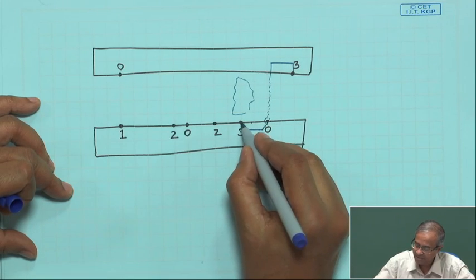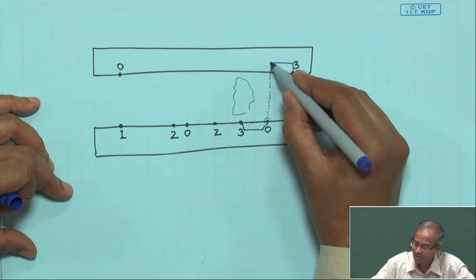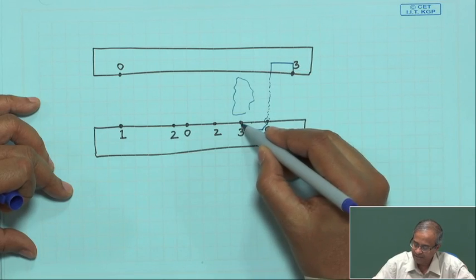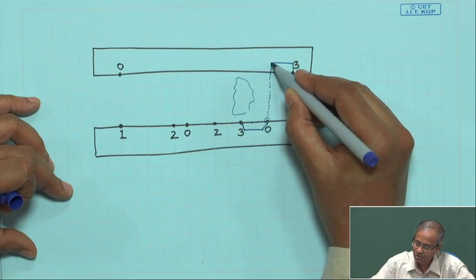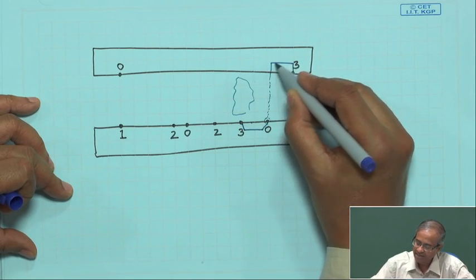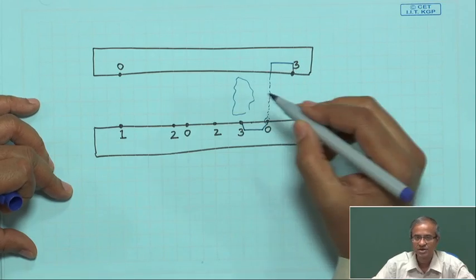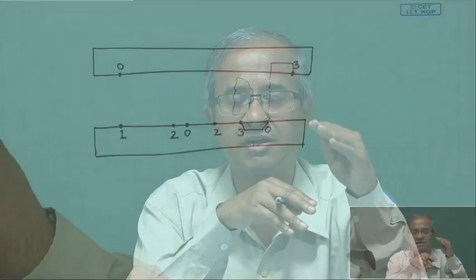And one thing is there: during over the cell routing you are not switching from one layer to the other. The entire net, both horizontal and vertical, is laid out on the same metal layer. This is one difference, because in over the cell routing you are not allowed to use via connections; you are doing it on the same metal layer, right.